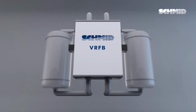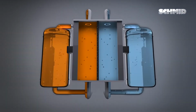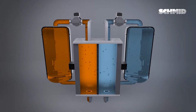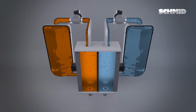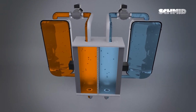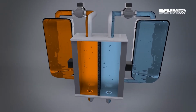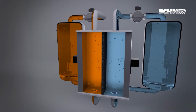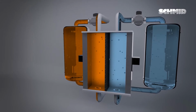The SCHMID Vanadium Redox Flow Battery consists of two tanks storing vanadium analyte and catholyte. Pumps are used to flow these electrolytes through adjacent half cells separated by an ion exchange membrane. Within the half cells, the electrolytes are chemically oxidized and reduced to reversibly convert electrical to chemical energy.